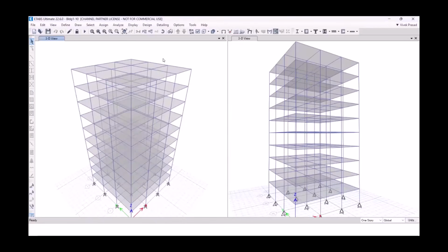So when you're performing the vertical acceleration, it should be noted that we'll be typically using membrane type floor slabs. So the masses are actually distributed, but the membrane will transfer loads to the frames. So the mass excitation should happen at the floor also. So you need to model the floors as shell in this case